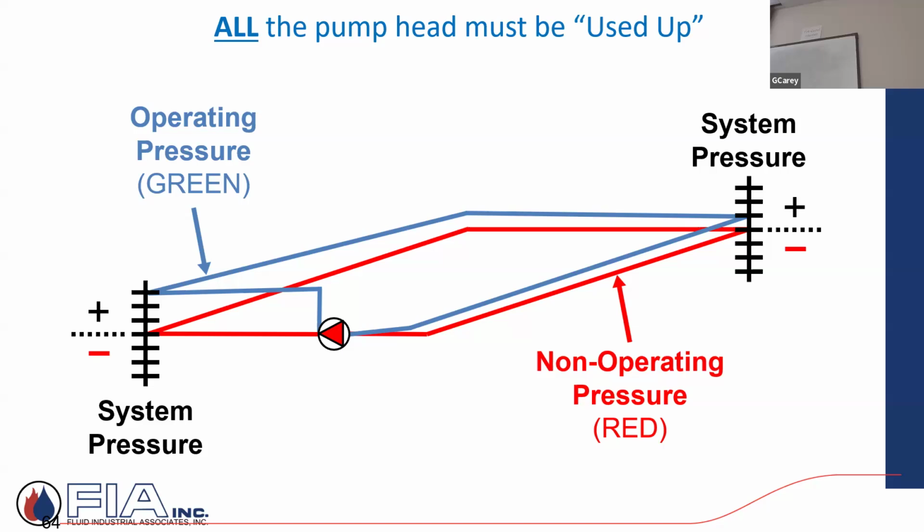What's happening? Friction. We're eating up the energy, which we sat on week 1 saying, hey, what's the flow rate? What's the size pipe? What's the pressure drop through that loop? Okay, I got to buy a pump that can do this many gallons a minute and create this pressure differential. And when I turn it on, everything being right, my greatest differential is right here. But as that flow takes place, there's frictional resistance that's consuming, that's eating up the energy that pump could develop.